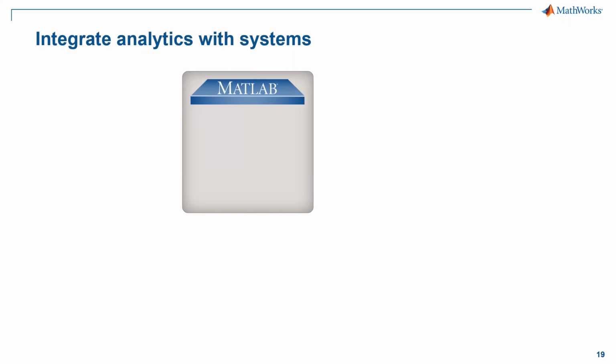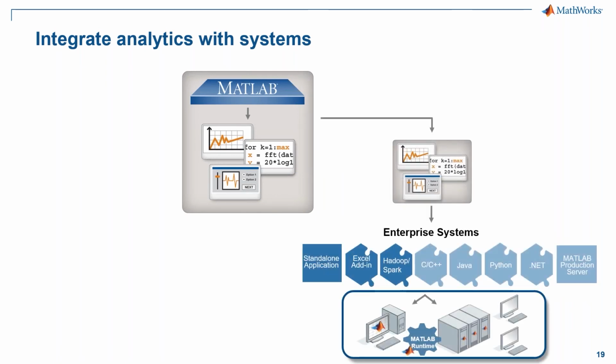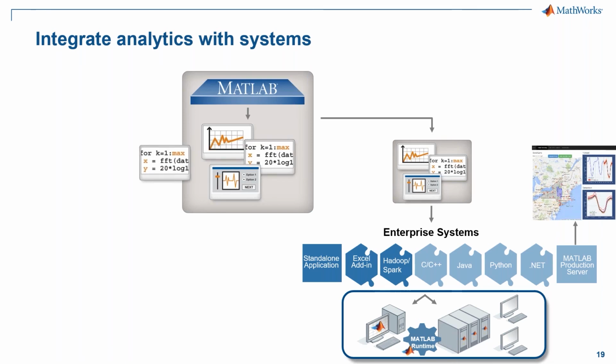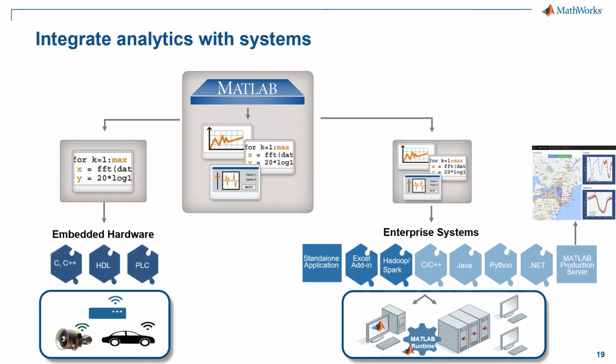Now, it's not enough to just build these in MATLAB. You do want to be able to integrate them where they're needed. So, with MATLAB, we've got a variety of deployment tools to allow you to deploy these models where they're needed. If you're looking to deploy onto, say, the cloud, then you can use our compiler tools to compile either a standalone executable, web application, or a variety of different software libraries to integrate with a potentially different front end. And if you want to deploy just the algorithm, say to an edge device or a microcontroller, then we do have code generation tools available as well to target embedded hardware for some of the models we talked about